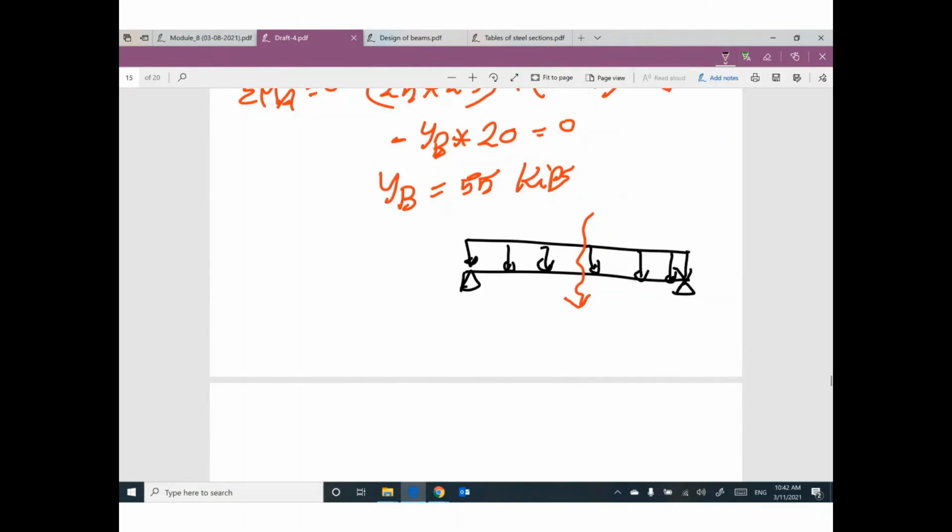But if you have a uniform distributed load with something inside, like a concentrated load, for example two concentrated loads, what should I do? You have to divide the distributed load into 3 parts, each part alone with its equivalent. Does that make sense?